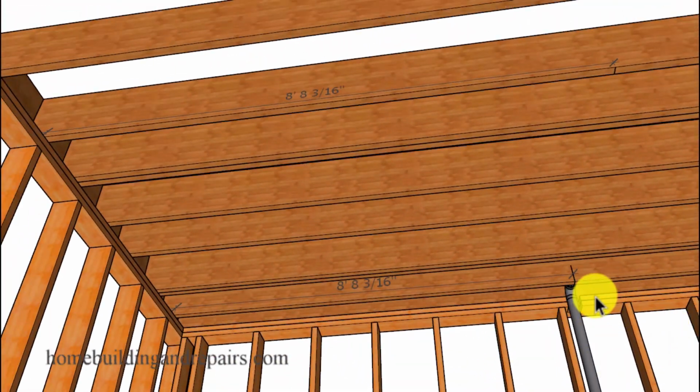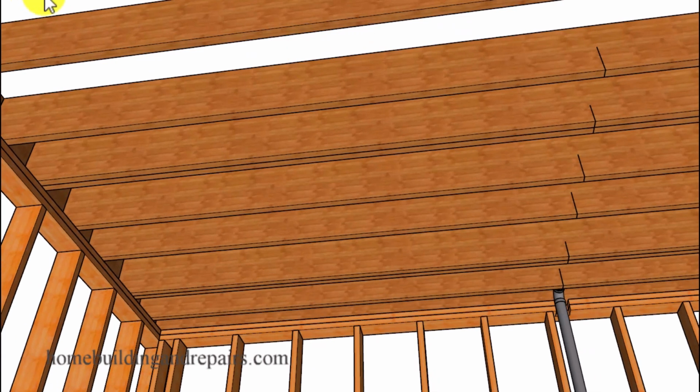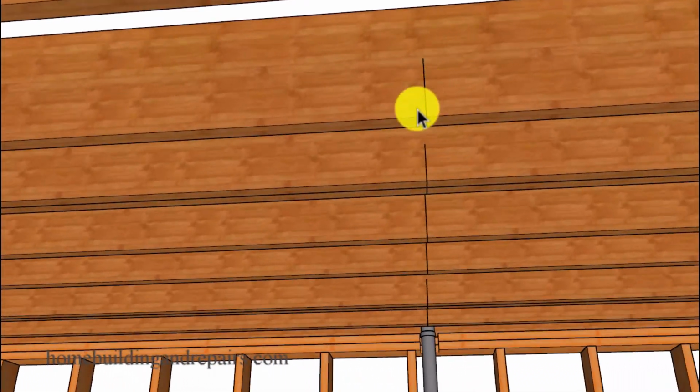So you would need to locate the center of the fitting here and then transfer that measurement to another joist that might extend a little further than you need to. Then we will use a straight edge or our chalk box to snap a straight line to connect the 2 points together. And then we're going to use a framing square or some type of a square or even a level to create a plumb line or a square line off of the joist.